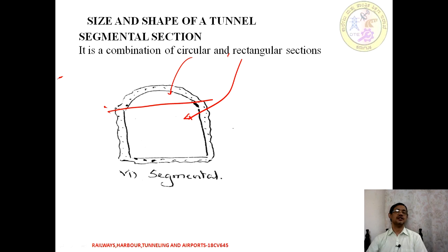As we know, different sizes and shapes are also possible. The width depends on, in the case of transport, how many lanes, and the width and height of a truck we are proposing. If it is a liquid, how much volume has to be discharged over a period of time along a length. Apart from that, if it is sewage or any liquid, self cleansing velocity and the shapes are considered in deciding the size and shape of the tunnel.